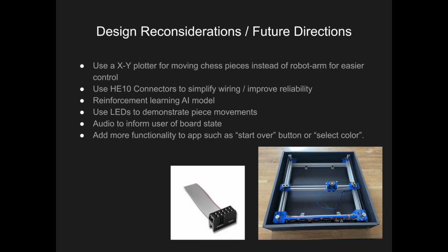Another consideration was using HE10 connectors instead of individual wires that caused issues from loose connections. This would greatly simplify the wiring nest that we created and help for future debugging. Other features we would like to include are an array of LEDs under each chess square for visual feedback to the user, such as which piece they moved or whether they're in check or not. The same could be applied for audio feedback as well.